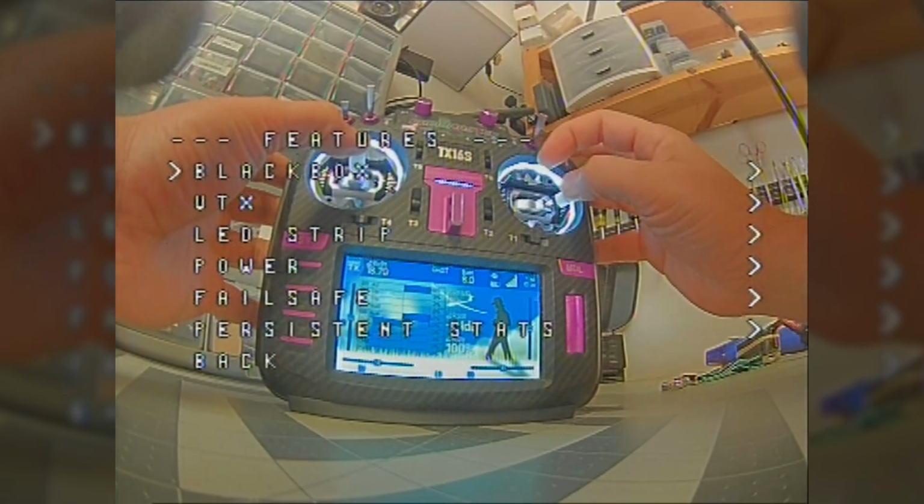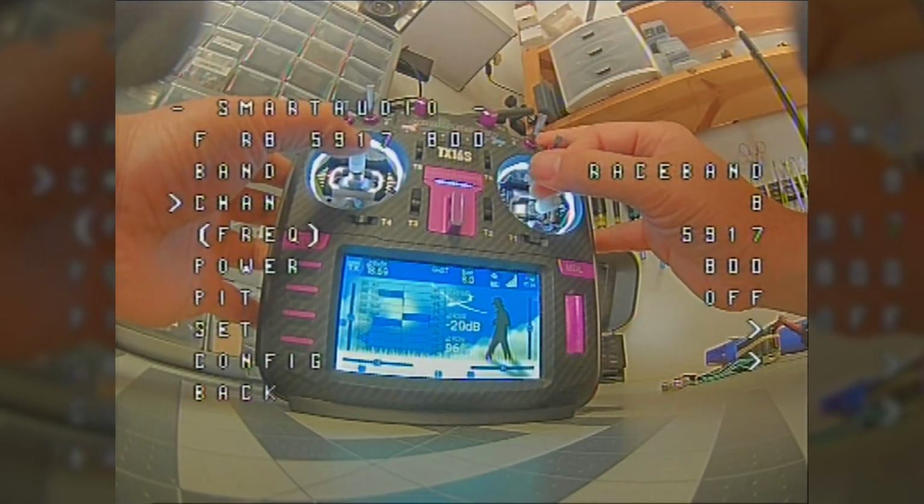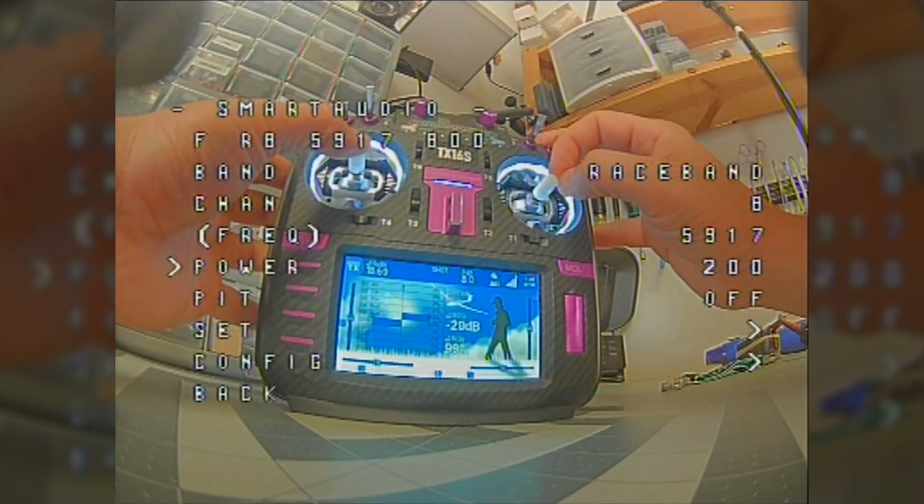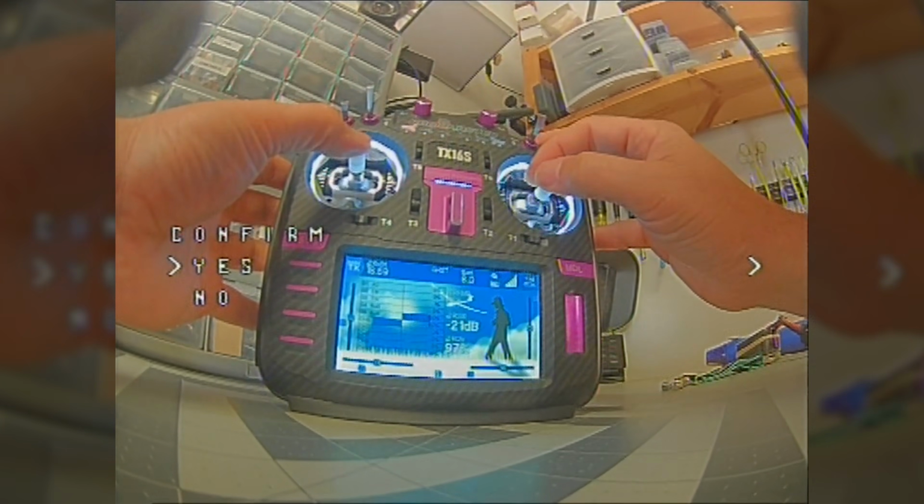And if you're flying with other people, a lot of times you have to move to a certain channel so that you're sort of coordinating your channels. And nobody wants to do that by pushing a button on their video transmitter. That's annoying. Instead, you can do it using your flight controller. You can pop up a menu in your goggles, and you can use your controller sticks to move around, and you can change those settings.